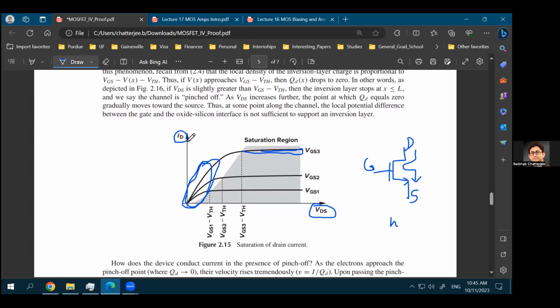Okay, so what we are going to do today first is this: in the last lecture, we tried to understand this ID versus VDS characteristic from an intuitive standpoint, from the point of view of the energy band diagrams. By applying a gate voltage, you're trying to reduce the energy barrier. Remember, we drew something like this in terms of the energy band diagram. This is the N region, this is the P region in the channel, and this is another N. This could be your source and this could be your drain, and the electrons are trying to flow from source to drain, but in between they see a wall, a hill. So the electrons cannot flow from source to drain, and you need to do something. What can that be?